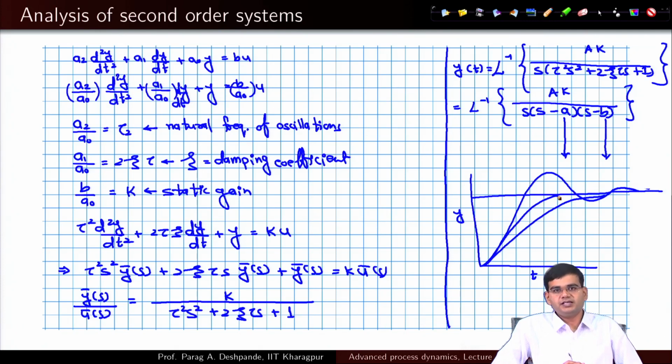So, we will stop here today. We looked into one particular case where the transfer function was of the form d1 s plus d2 upon d3 s squared plus d4 s plus 1, right, which means that there was a polynomial in the numerator as well as a polynomial in the denominator, and the very definition of the order of the system became questionable, because you not only have the polynomial in the denominator, following which with the help of the degree of the polynomial you could determine the order, you have a polynomial in the numerator as well.